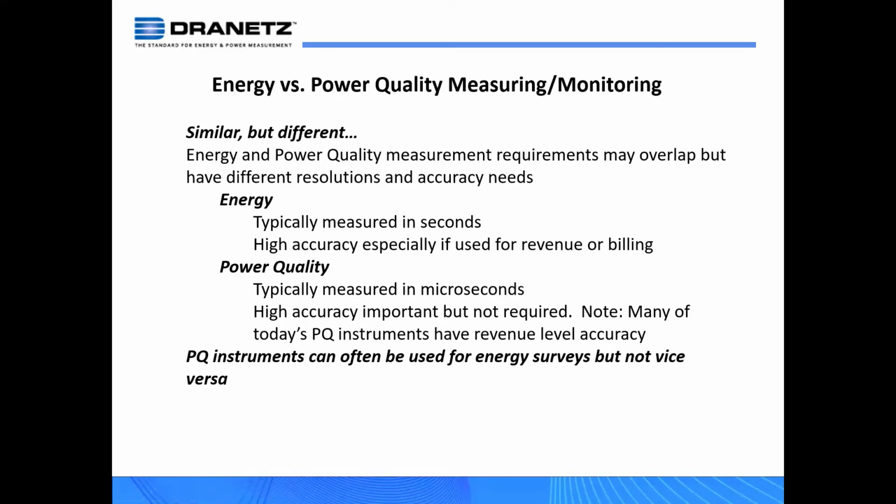Sometimes what I've learned in this business is that you do get what you pay for. So although the energy meters might be a little less costly, you wind up paying more in the end if you have what I call misapplied technology. So I have a meter that's designed for energy management applications, but I'm trying to use it in a power quality application. And again, I'll be disappointed with the results.